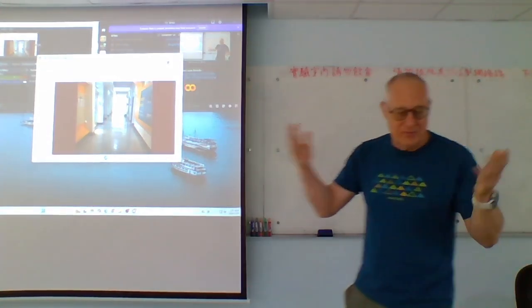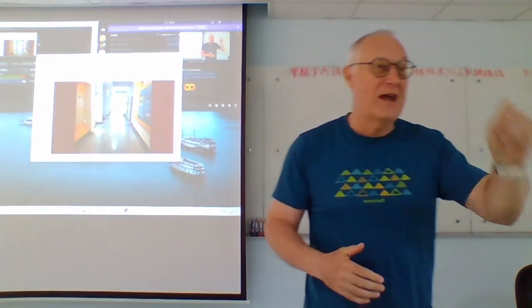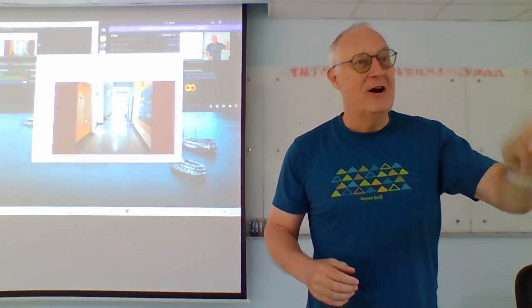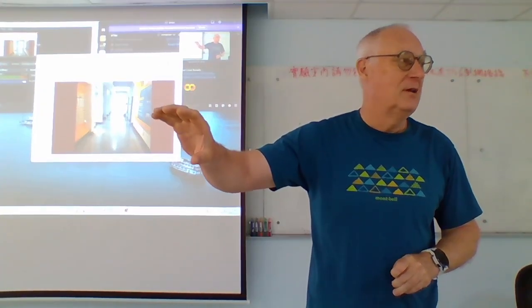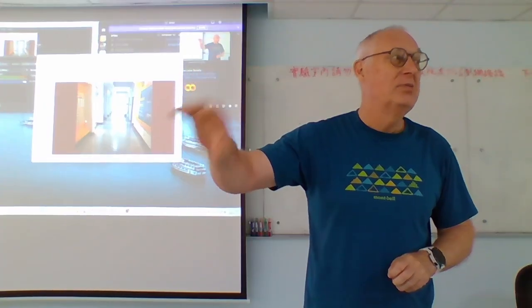it's like the way that we build algorithms, right? We're trying to track pixels. So we're trying very hard to find the new position of the pixel. But if that pixel disappears, then I'm trying very hard to find some other location that is still reasonable, which will then be completely wrong, which usually ends in catastrophic failures for a robot, because the robot thinks that there's now obstacles everywhere. It's refusing to move anywhere. So the first reason is that pixels in the center of the camera are more likely to remain within the frame.